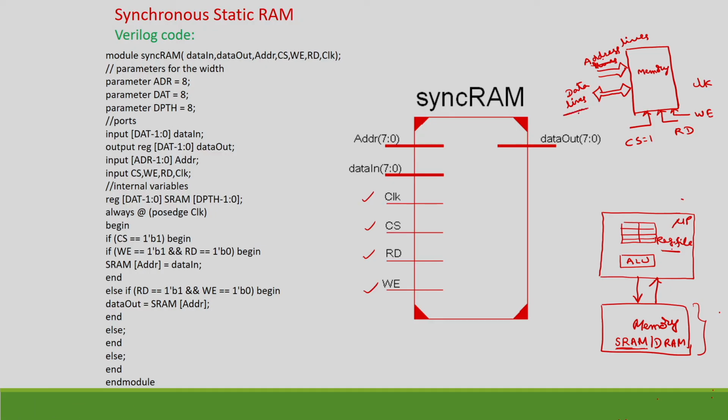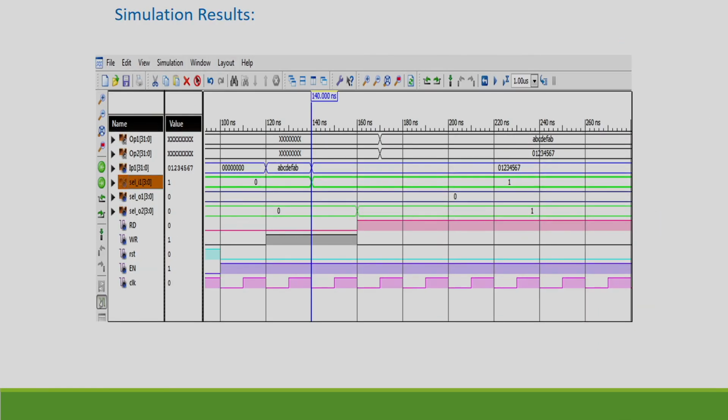So, these are the write enable signal, read signal, chip select signal, and clock. Then the data, as I have told, is bidirectional. Data in is in this direction, where data is inputted, and data out is in this direction. This is inside and this is outside. Similarly, there will be some address lines, which are unidirectional. These address lines decide the size of the memory.